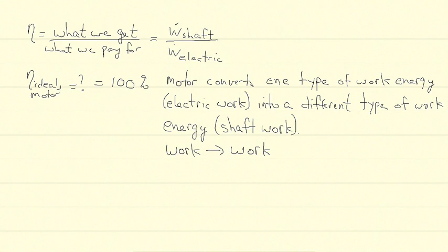If you remember the second law equation, it essentially states the following: dS is equal to Q dot divided by T, plus the sum of m dot i times s i, minus the sum of m dot e times s e, plus entropy generation.